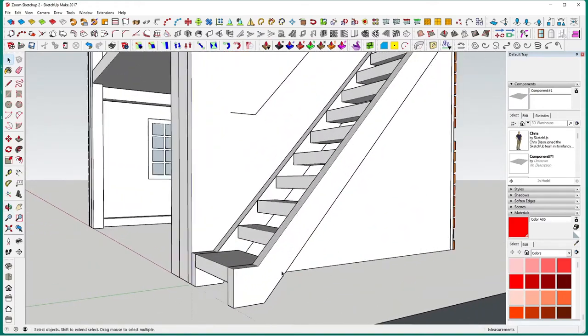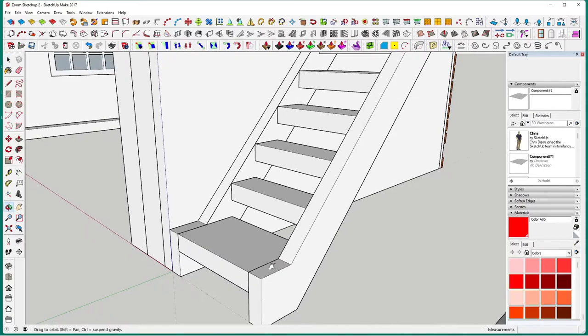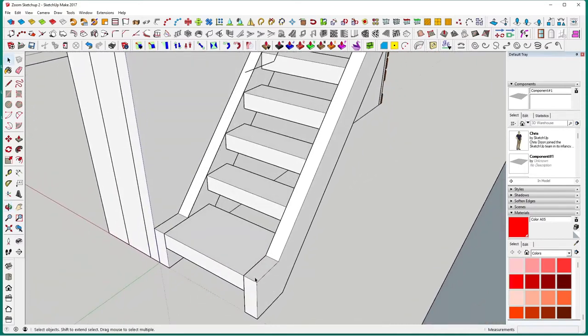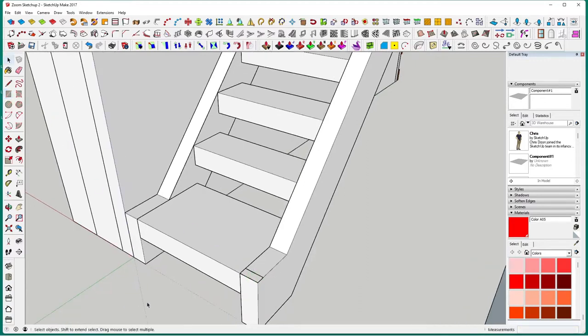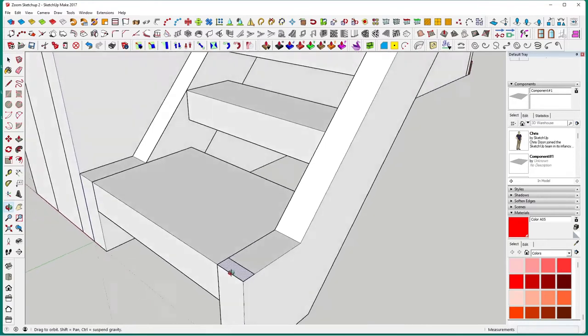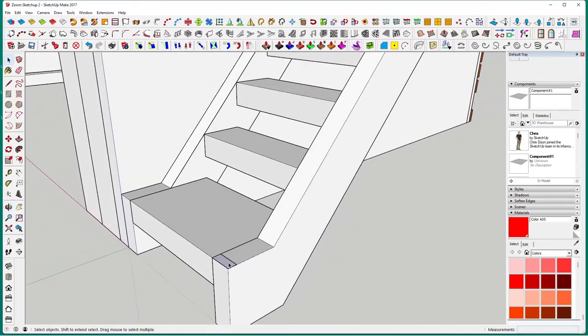Next we want some spindles. Now because we're going to print this, hopefully FDM, we'll go down to the bottom, we'll get a rectangle tool, come across, in the dimensions we'll go 0.1, 0.1, comma 0.04, enter. Now that is the same thickness as our glazing bars, and if you can print your glazing bars you can print your spindles. Double click.